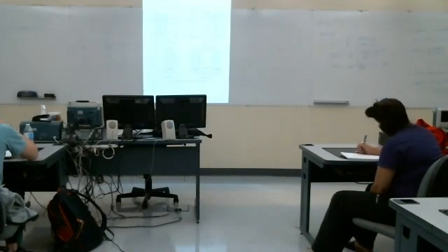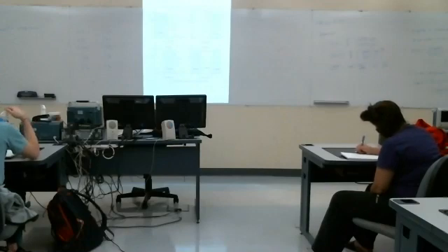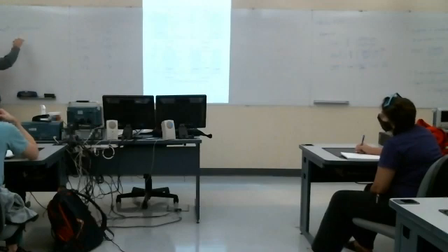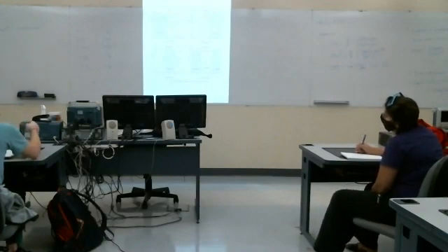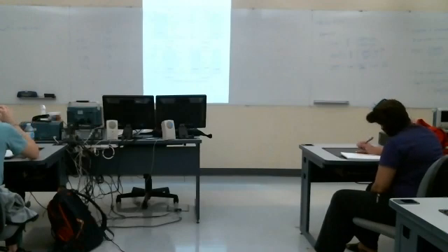So we effectively just ignore the 1 and say for frequencies to the right of omega c, we're going to approximate our frequency response using this simpler equation. Now that equation actually is really simple if we work in decades.